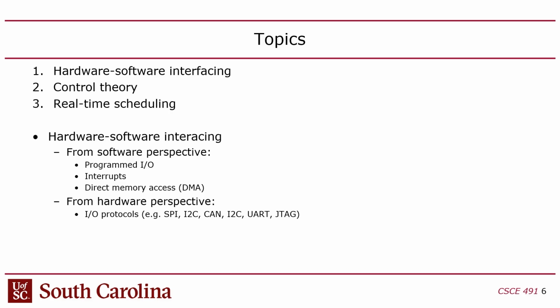But basically, these addresses are physical addresses where if you write to them, you're not writing to memory. You're actually bypassing the memory, and you're going to an I/O device, some kind of a peripheral. And if you read from those address ranges, you're not reading from memory, you're reading directly from a device. Yes? Would this be considered like SRAM? No, well, maybe. They're usually referred to as registers, control registers and status registers. But technically, I think physically, they're built with SRAM in the peripherals, I think, generally.